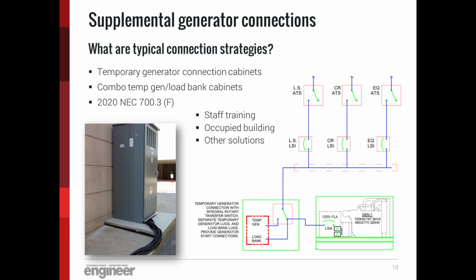Now, if we're going to do supplemental generator connections, i.e., an external load bank or an external generator connection like you see imaged in the bottom left, it can look a variety of ways. And one of which is you could actually put a transfer switch that allows for those external connections to be either a temp genset or a load bank. Now, David, what are your concerns associated with using equipment like this?